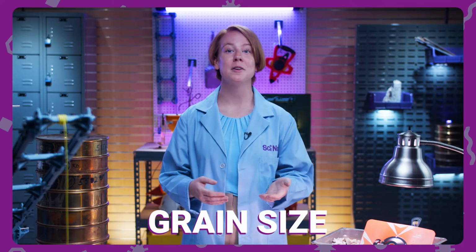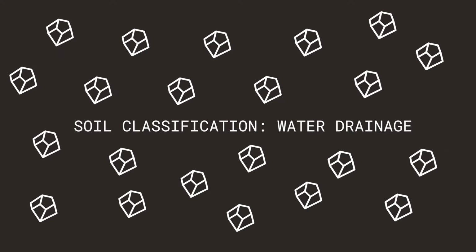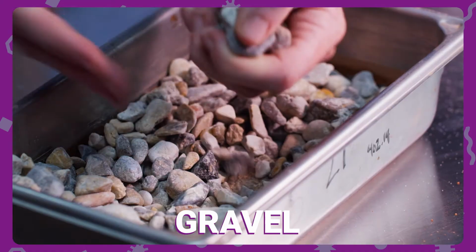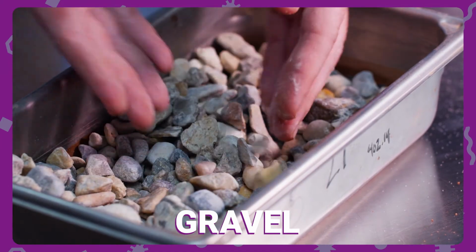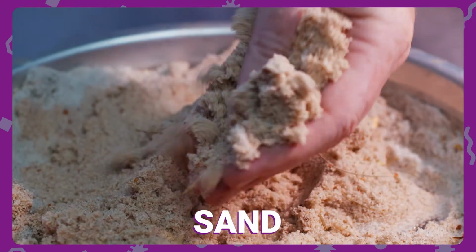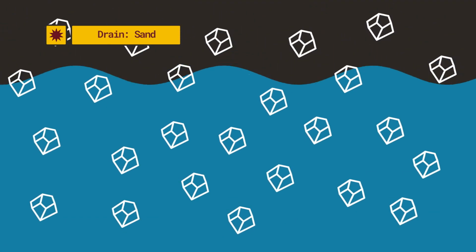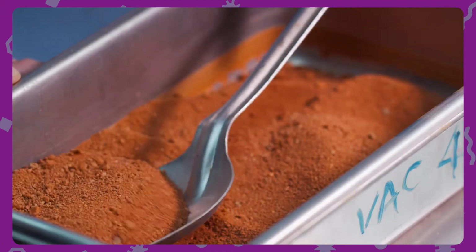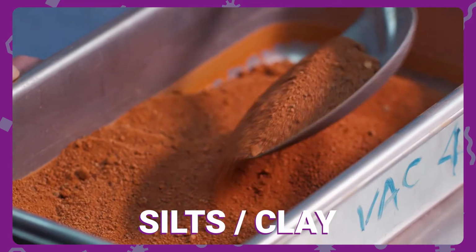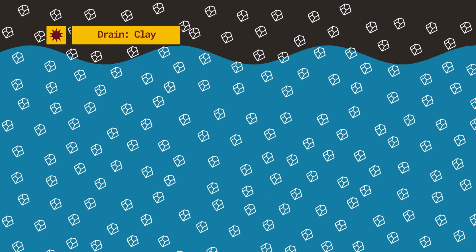Earlier we talked about how soil is classified by grain size. Another way to classify soil is by the drainage of water, which depends on how large the particles of soil are. Layers of gravel drain very quickly because there's room for water to pass through. We can see here that the particle size is very large. Sand is the next best soil for drainage. Sand's particle size is smaller, so it takes longer for water to pass through. Finally, we have silts and clays. Their particle size are so small that it naturally compacts, and there's not a lot of room for water to pass through.